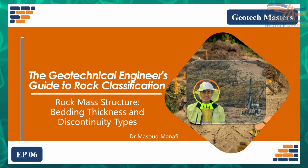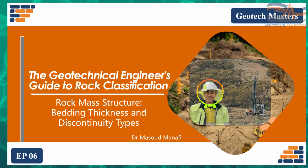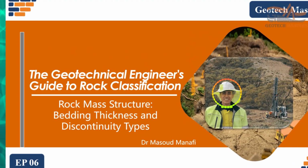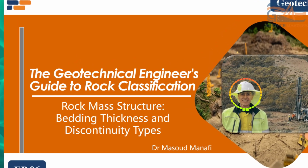But today, we are going to zoom out. We are going to look at the rock mass. In geotechnical engineering, the rock material rarely fails. It is the cracks, the layers, and the breaks between the rock blocks that usually cause problems.